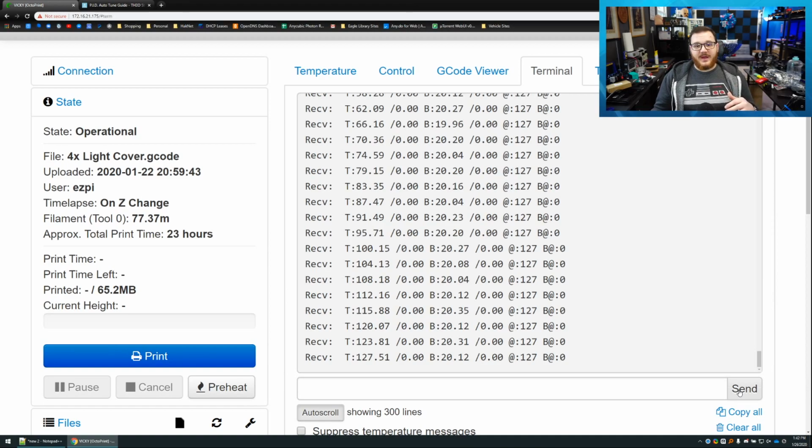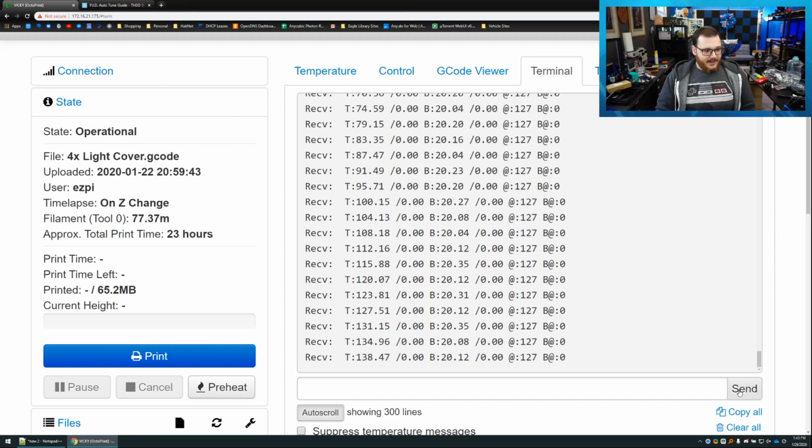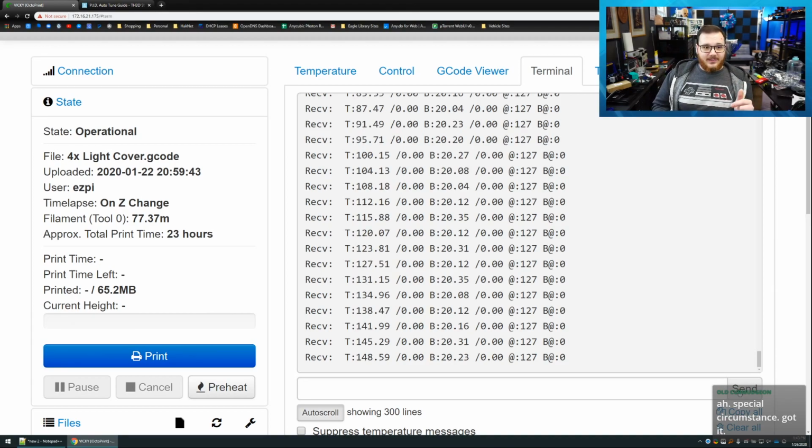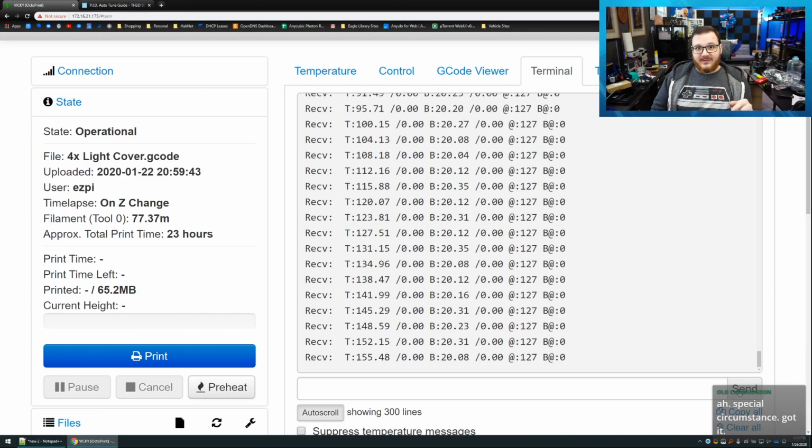But I want the board to be powered because there's a pin on the board, and that's an MKS Gen 1.4, a really old board, that can pull to ground or pull high. The ATX PS_ON wire, which is the green wire traditionally on your ATX power connector, is connected to that pin, and Marlin has an option to control an ATX power supply.